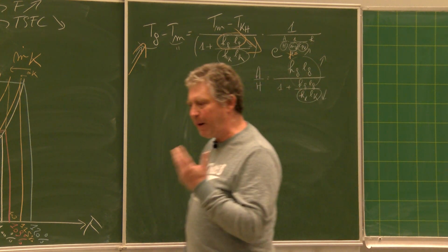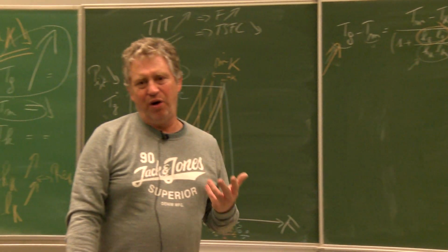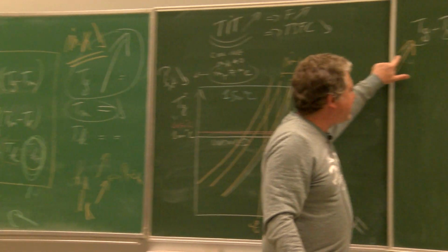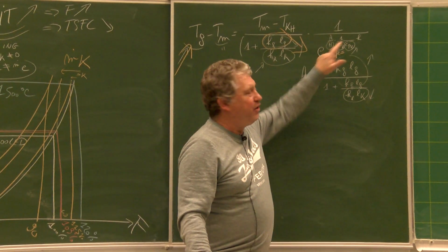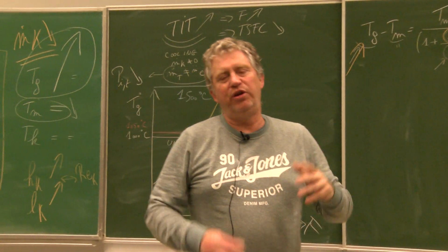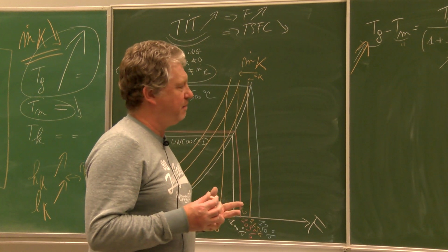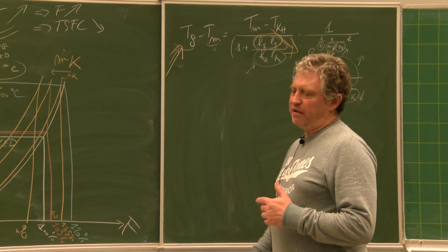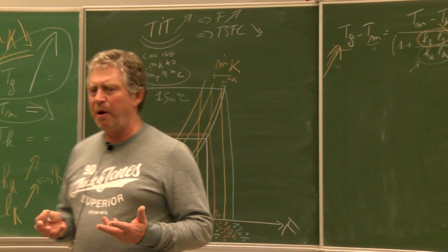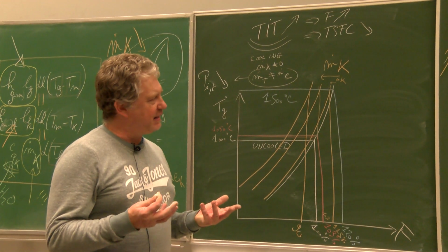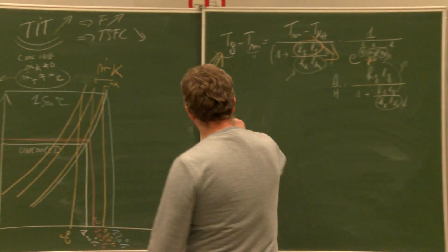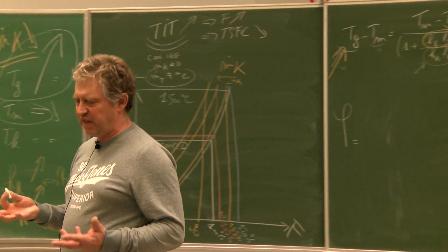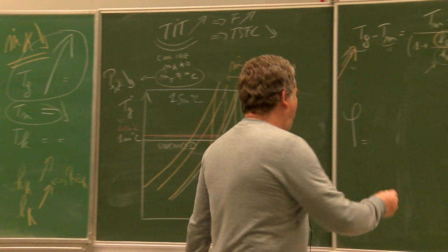So you see that you play with the technology in order to improve the performance of the engine at 2 levels, increasing T_g and not increasing m dot k, or not too much increasing m dot k. And the parameter that is commonly used in order to compare these different technologies and these different factors is what is called the cooling effectiveness. This is a sort of efficiency of the cooling. And how can we define